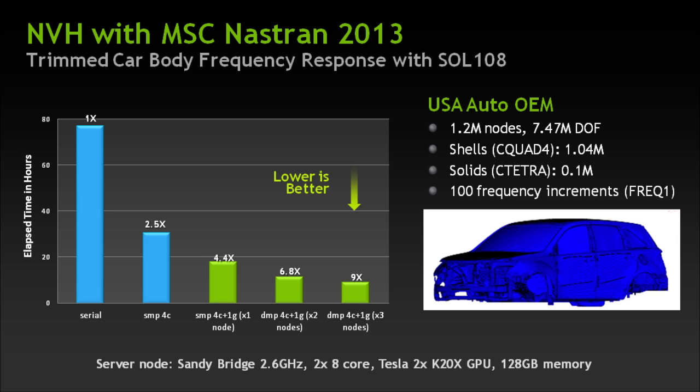Now, the thing to emphasize here, this was asked in the earlier conference call this morning. In terms of model selection for GPU acceleration, fundamental to GPU computing is having enough work for the GPU. Solid models tend to create blocky fronts that are very attractive as far as the solver work in terms of computation. It provides dense fronts and lots of computing for the GPU. But when you look at shell models, or the combination of shells and solids, it's not that these are not going to be GPU accelerated. You still see good scaling on these.